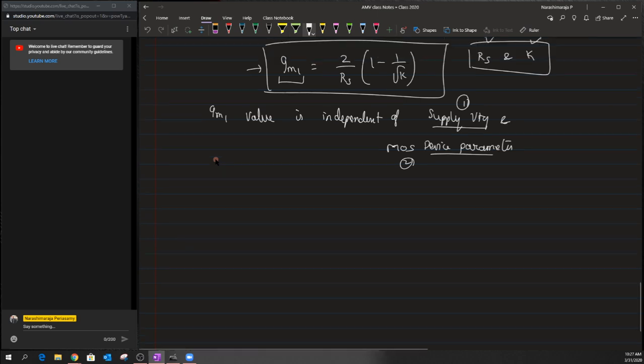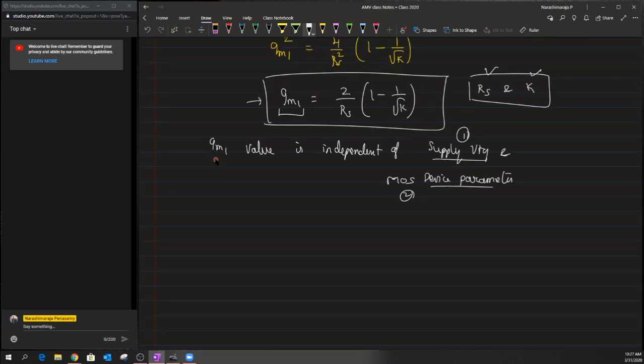There is some sort of flaw in this particular circuit, just because the value of RS is quite sensitive to the temperature, but one could replace this RS with some sort of switched capacitor network. Probably we'll talk about the switched capacitor network, which mimics a resistive element, when we discuss the switched capacitor circuit in the next coming classes. But obviously one could really achieve a constant GM1 as well as all other GMs through this network.